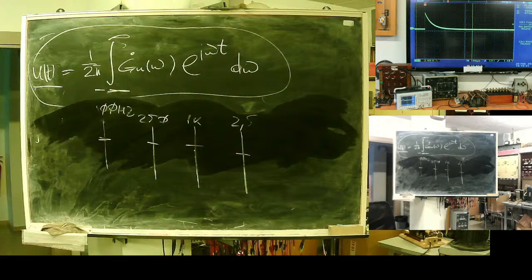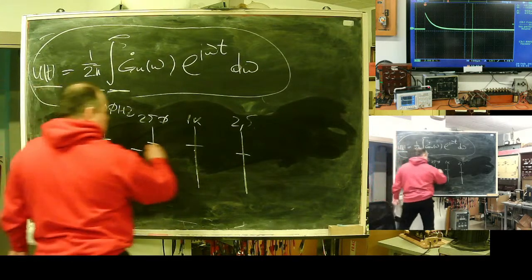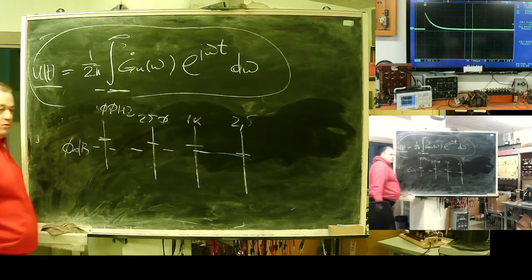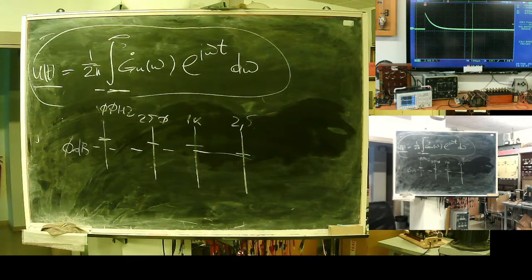What is it a function of? On the vertical axis, this is the amplitude, either decay or amplification: 0 dB in the middle, below is decay, above is amplification. And what will be on the horizontal axis? Frequency, of course. It's a function of discrete frequency.